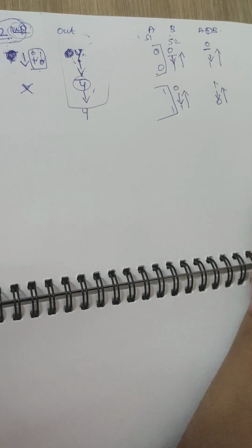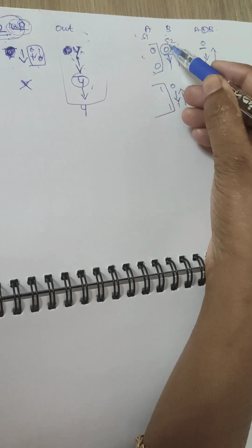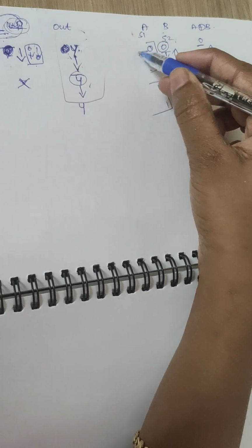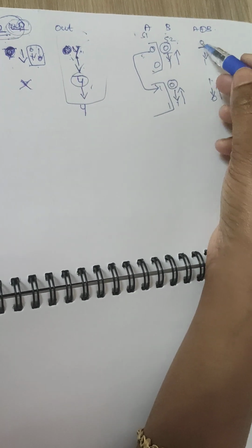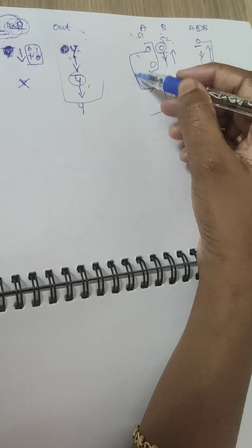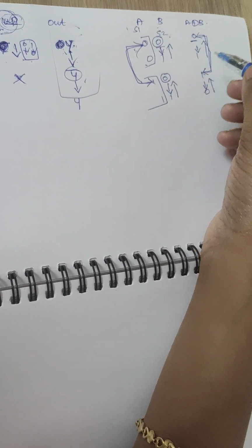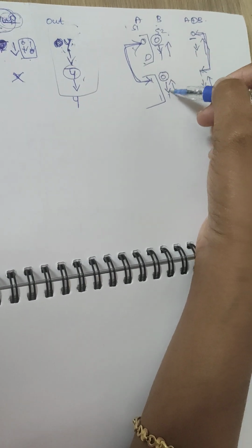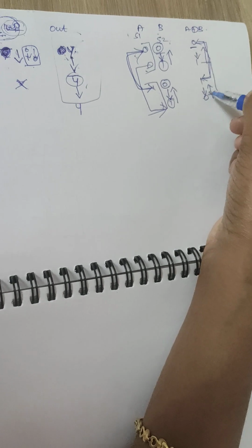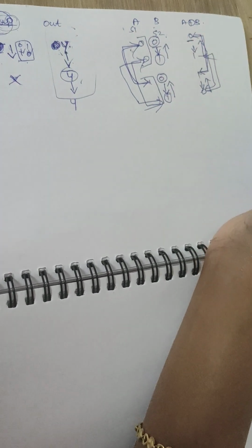Okay, so same as the case with S1 also. Here it is 0 and this is 0, right? So S2 is constant now. If you change this input from 0 to 1, your output will also toggle from 0 to 1, and if it becomes 1 to 0, your output will become 0 to 1. Same as the case with the 1 also. So here and here it is the same. If it is changing from 0 to 1, your output will change from 1 to 0, and if it is 1 to 0, this will change from 0 to 1.